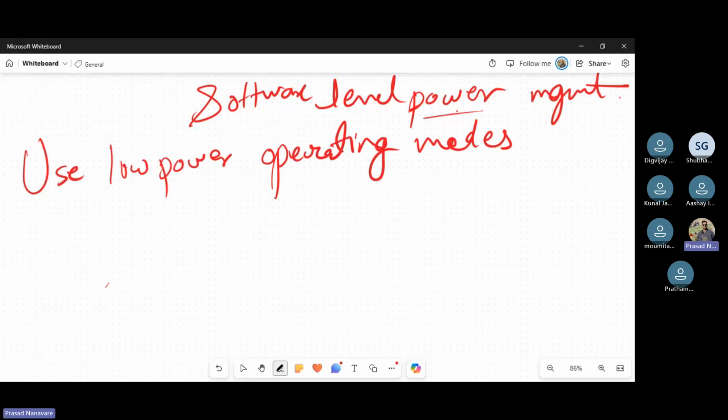The sleep mode is basically the processor core is powered down, but certain peripherals remain active, such as timers and communication modules. Okay, then there is deep sleep or power down mode. So in that mode, we have the entire system, including peripherals, powered down with only essential components like wake up sources, like interrupts, being active. So if the interrupt comes, then only wake up the system. There are wake up triggers available.